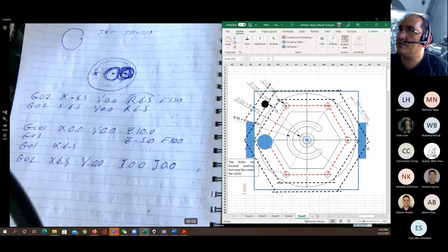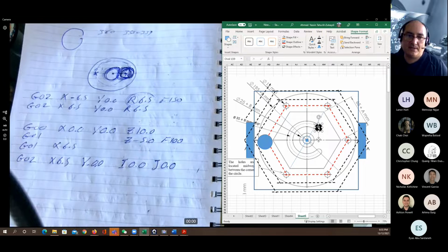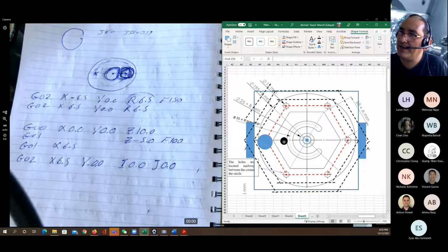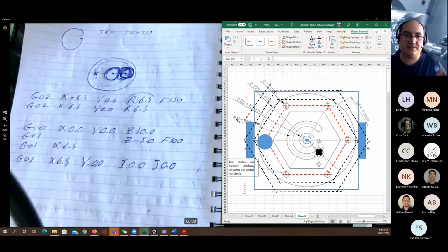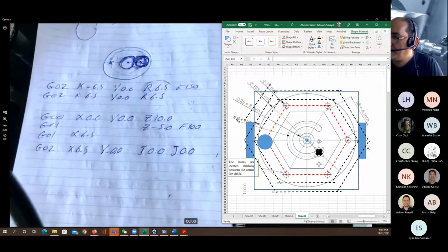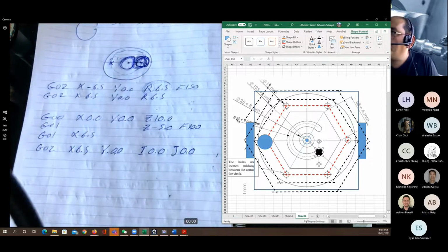So now G00, going to the top of this position. G01, get inside. G02, sorry, if I'm here, G03, and find the location of that point. So this will be the movement that's going from here to here with the radius, which is equal to 35 millimeters. That's it, very easy. So to cut the C shape, I will consider that point to be 35 multiplied by 45.